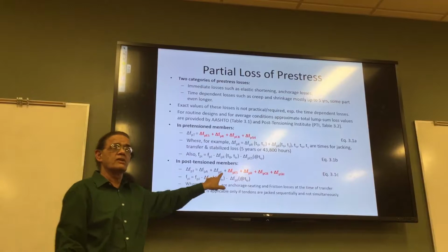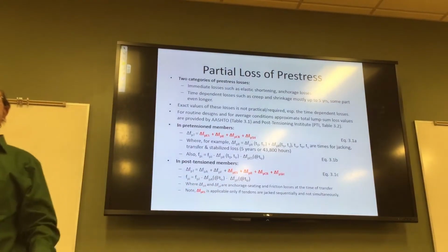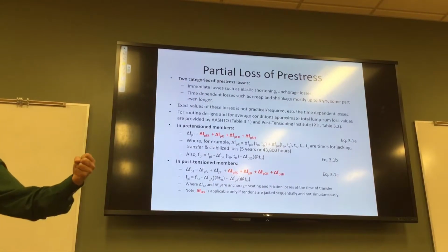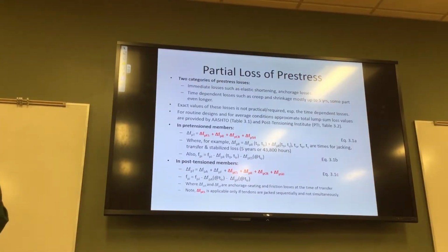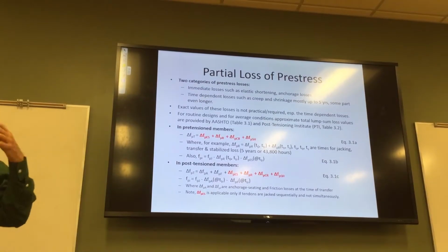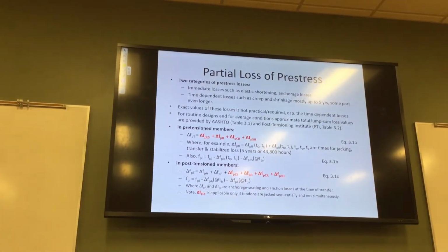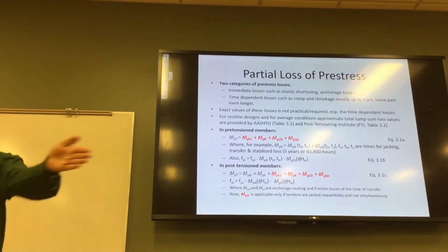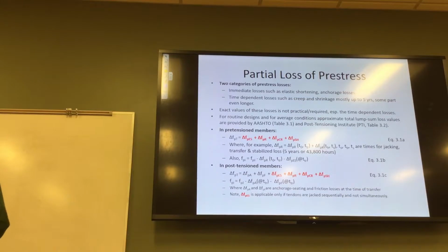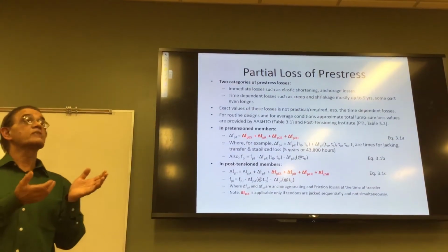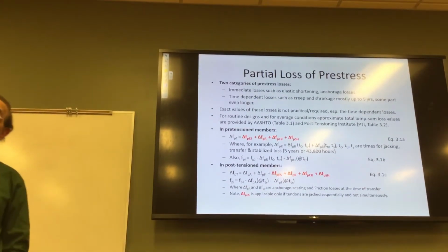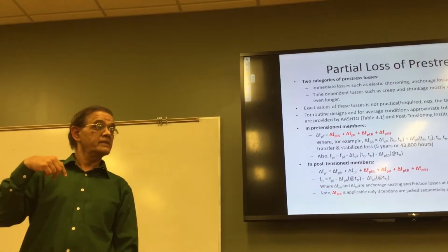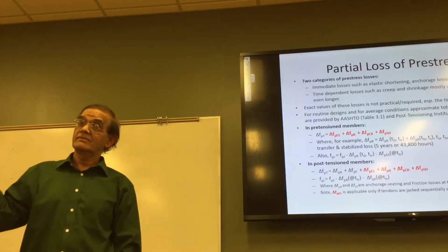This other one is the friction loss. As you stretch this inside a duct, depending on how many spans you have, and you're pulling it at the end, well, the cables or the strings, or what you want to call it, the strands and the wires, the braided wires in other words, are going to rub against the inside of the duct depending on the material. If the duct is lubricated, or if the duct is Teflon lined, right?